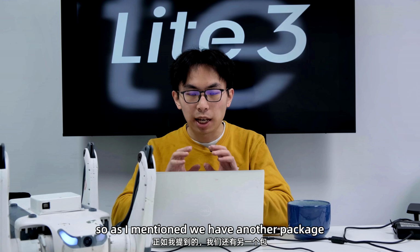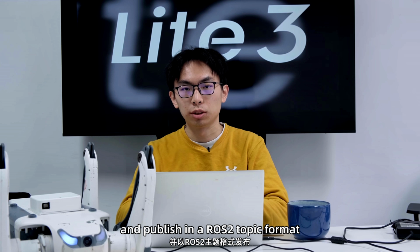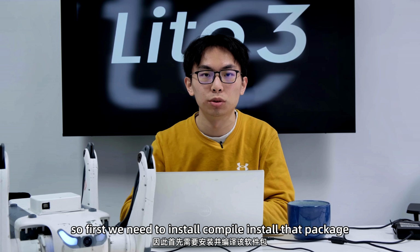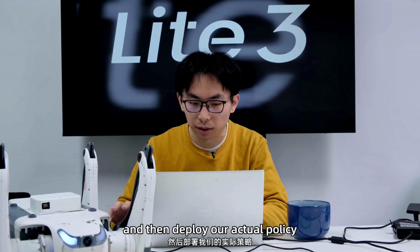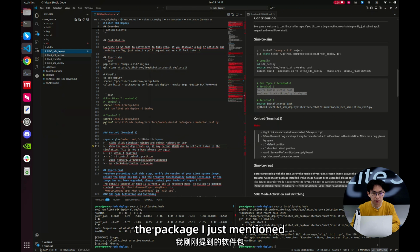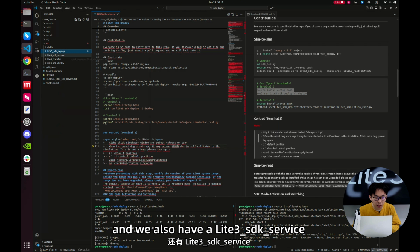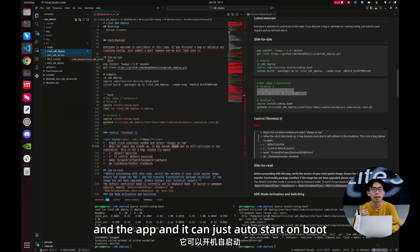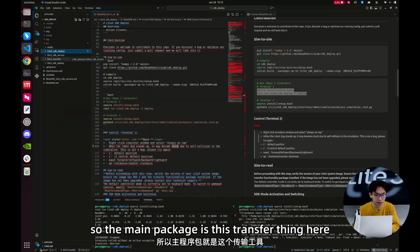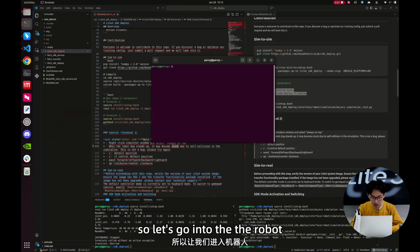As I mentioned, we have another package that gets the UDP data and publishes in ROS2 topic format. First, we need to compile and install that package, and then deploy our actual policy. The package I just mentioned is the Lite3 transfer here. We also have a Lite3 SDK service that communicates between the robot and the app, and it can auto start on boot. The main package is this transfer package, but we need to compile this Lite3 SDK service too.